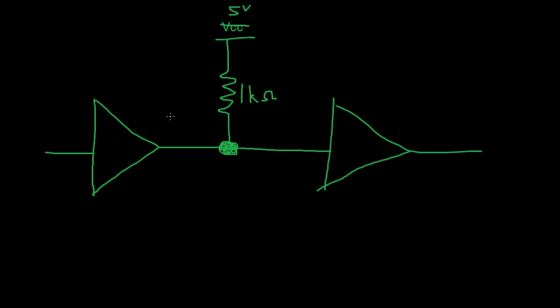I mentioned power consumption because of that pull-up or pull-down resistor, and I just wanted to show an example of that as well, because it's a question I've had asked to me. Let's say you have a 1K ohm resistor operating at 5 volts. Our input device is also operating at 5 volts. Now, how much power is this resistor going to be drawing?